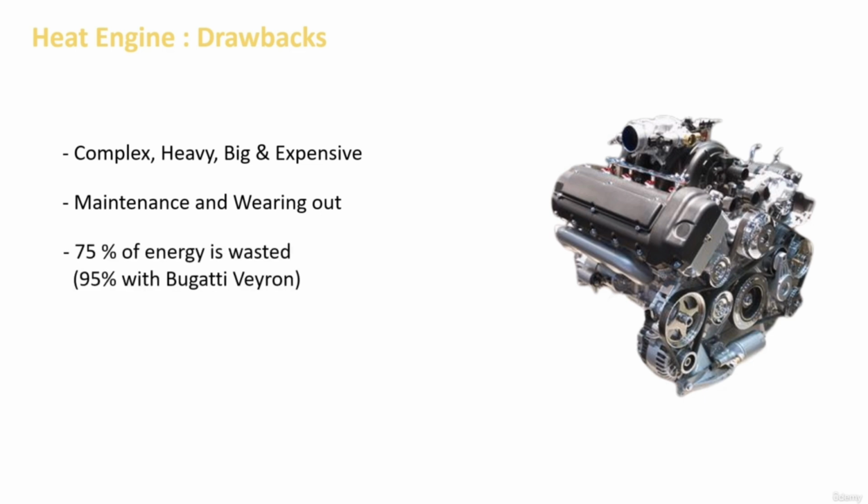In theory, we could improve the efficiency to about 50%, but that would mean a couple of things. Firstly, the engine would become more expensive. Secondly, it would have to run at a constant number of explosions per minute, which is very hard to do in the real world. Finally, the motor should be run at almost maximum power.